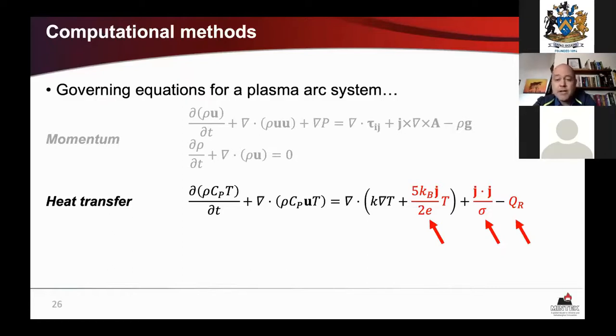The plasma radiation term is normally a really strong and nonlinear function of temperature and wavelength, and it's usually described using highly specialized numerical submodels for thermal radiation. Solving the radiation field can actually be the most expensive part of an arc calculation. It's quite hard to get right.